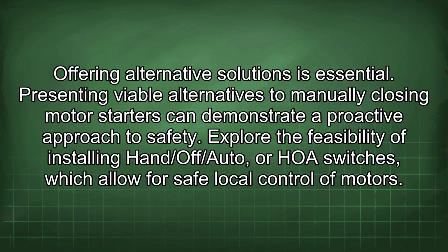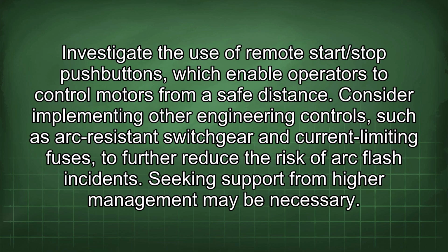Offering alternative solutions is essential. Presenting viable alternatives to manually closing motor starters can demonstrate a proactive approach to safety. Explore the feasibility of installing hand/off/auto, or HOA switches, which allow for safe local control of motors. Investigate the use of remote start/stop push buttons, which enable operators to control motors from a safe distance. Consider implementing other engineering controls, such as arc-resistant switchgear and current-limiting fuses, to further reduce the risk of arc flash incidents.